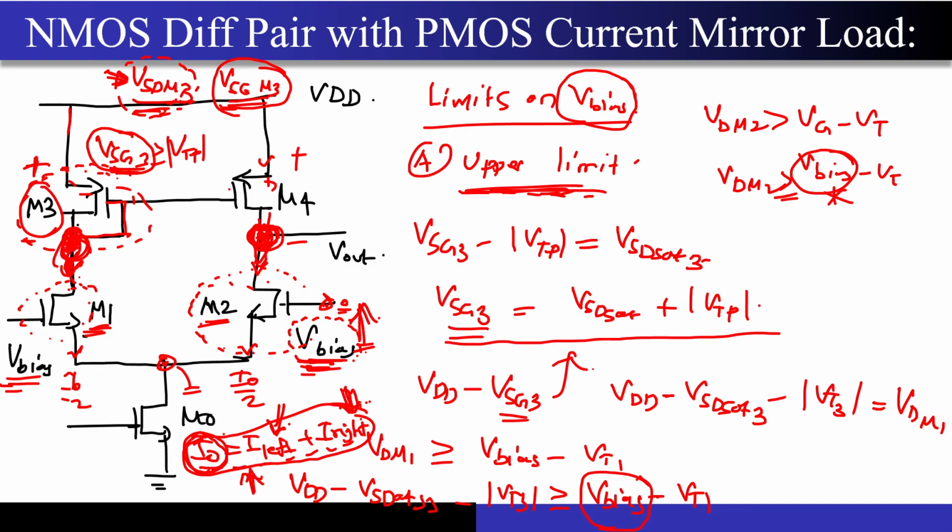So if one of the currents increases over here, the right hand side current will also increase, and then their sum will not remain I0 anymore. We are doing the constant current biasing over here, remember. So that is why these two nodes have to be at an equal potential.